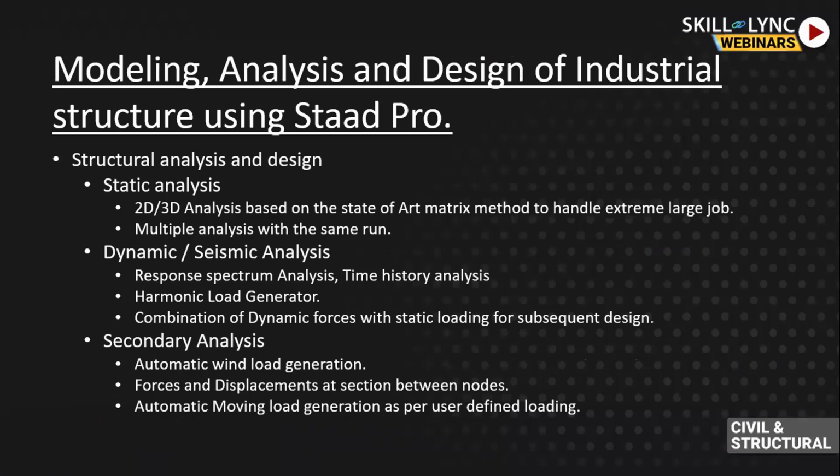Basically, the matrix method is used in analysis in Staad Pro. For foundations and plate designs, you also have the FE analysis in Staad Pro. And for seismic analysis, you already have built-in features in Staad Pro for seismic response spectrum analysis and time history analysis. And you have a harmonic load generation module also in Staad Pro for seismic analysis.